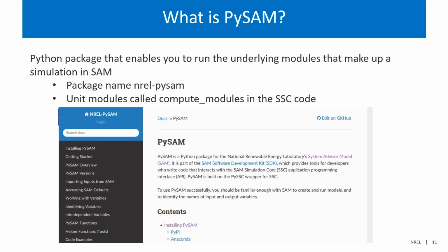So to get into a little bit more depth, PySAM is a Python package that enables users to run the underlying modules that make up the simulation in SAM. If you're going to download this into your Python environment via pip or conda, the package name is NREL-PySAM. If you just download PySAM, you will get something else. But instructions for that are on the PySAM repository, which we'll have a link to at the end of the slides. And within PySAM,